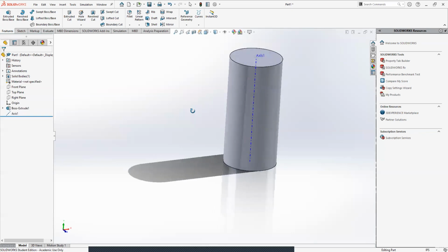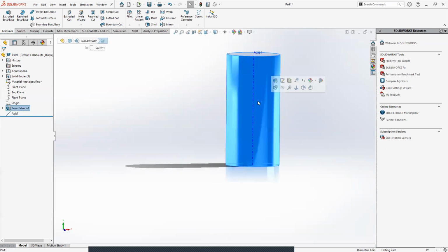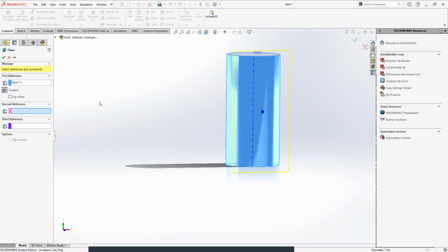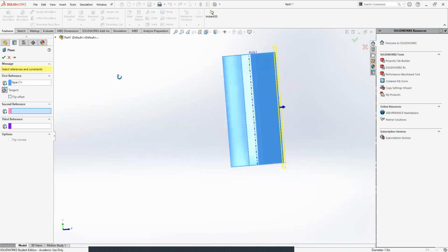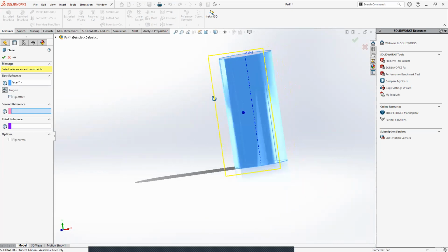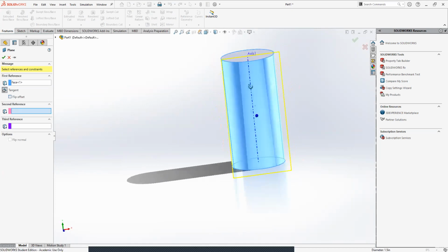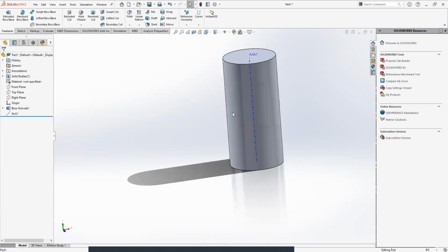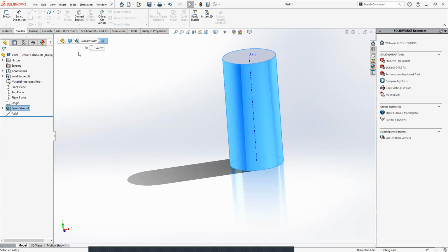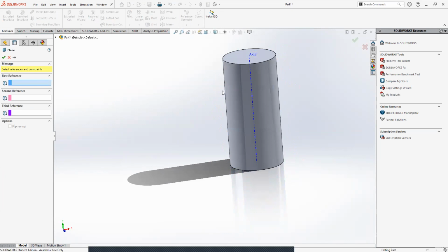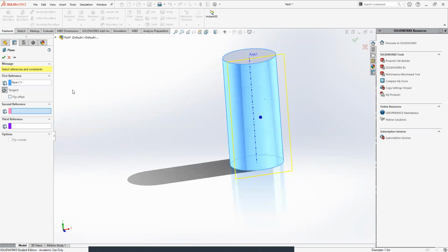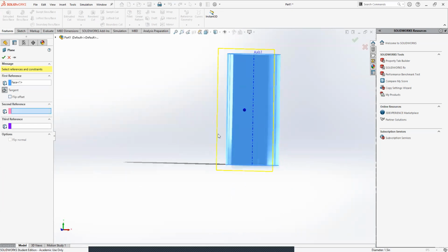Look at that. Now, another thing we can do with reference geometry, which I think is far more powerful, is the planes. Planes are very powerful. So let's say I wanted to make a plane that's flat on this face, so I can make a drawing on it. Because notice if I click on this face and I hit sketch, it won't let me do it. So I need a flat plane there. So let's make a plane on this surface. See how it's tangent, but it's not fully defined. It says I need to select more references.